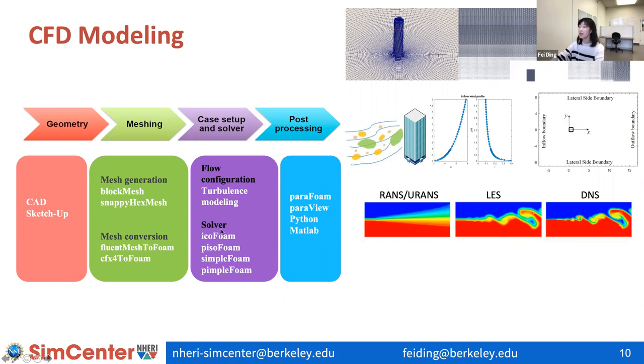You also need to select the numerical solvers to solve with the finite volume method. For example, pisoFoam is for transient and incompressible flow, and simpleFoam is for steady-state and incompressible flow. You need to choose the appropriate solver for the computational simulations.